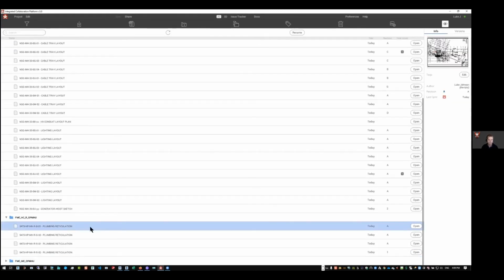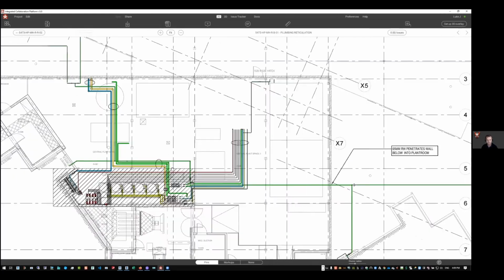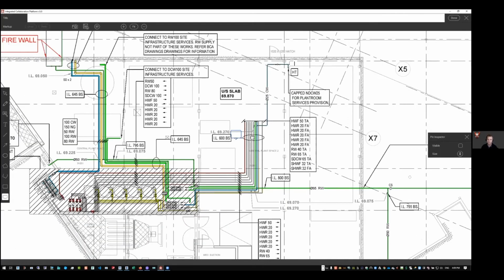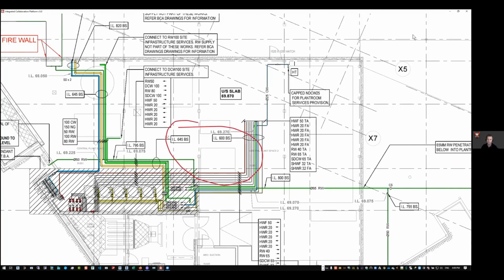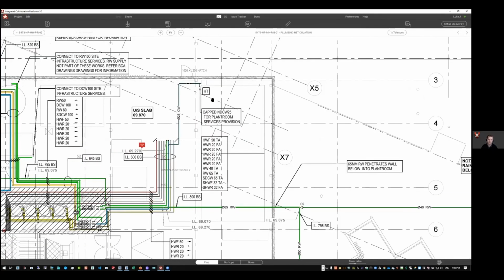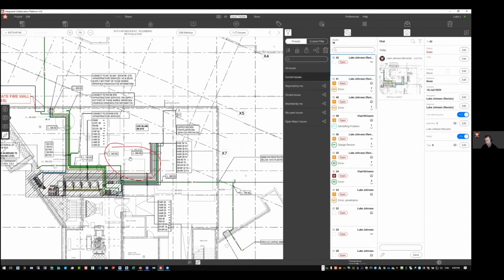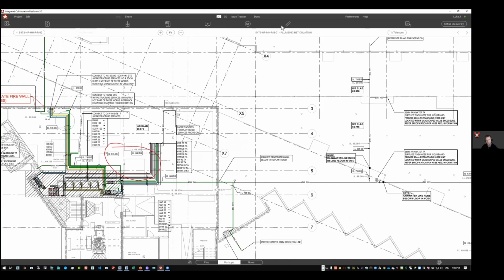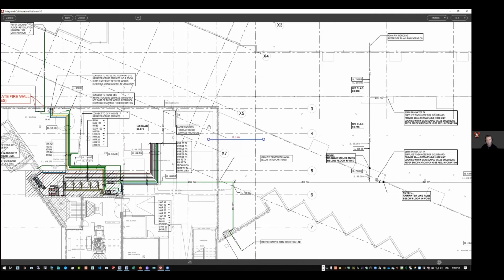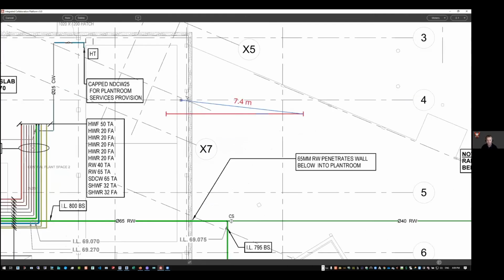Inside the 2D drawing space, we can view drawings as we've talked about. We can mark up on top of the drawing, so we can use Revisto to replace 2D markup workflows. We can just do plain markup straight on the sheet. We can drop stamps on the sheet as well, and then we can export from the drawing sheet straight into PDF with all the markups showing. On the drawing, we can also measure, and this will be a calibrated measurement based on the BIM scale of the drawing, and we can create multiple dimensions, and it's snapping to the vector lines on the PDF as well.